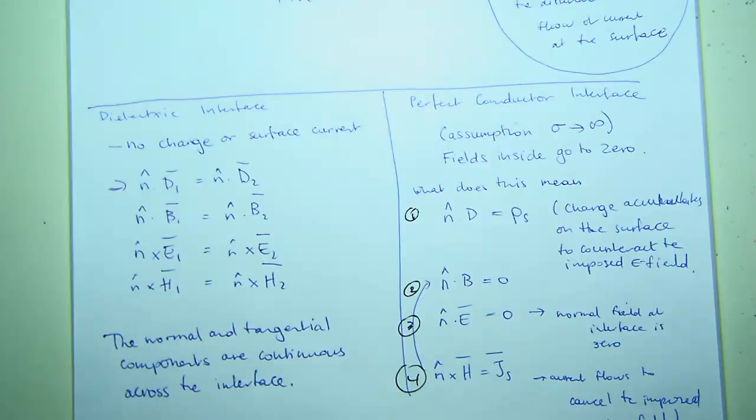So, during your first job, when you're asked, hey, undertake some very sensitive experiments for me in order to work out the sensitivity of this new great chipset or new phone that you've produced, make sure that the shield, which is the Faraday cage that you produce, is actually appropriately grounded. So yes, you need it to be a conductor. If it's a dielectric, it won't work to begin with, no matter how you ground it. But if it's a conductor, make sure that it's grounded, so therefore you can actually get some level of shielding.